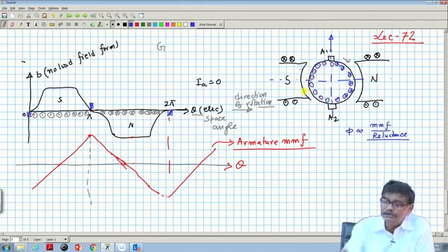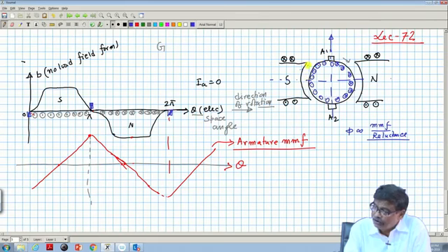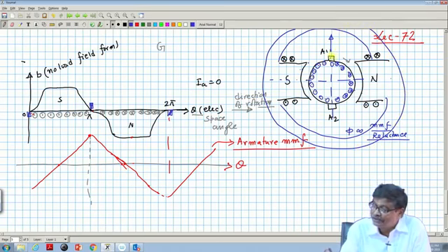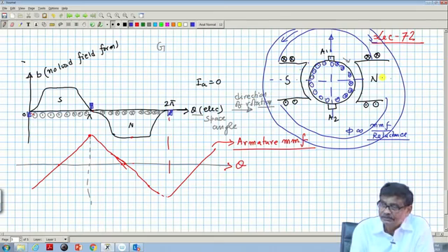But in case of a DC machine, one interesting thing happens. The air gap is more or less constant between this zone, but after that the air gap will be very large, because this is the yoke portion where the air gap is very large. Similarly, although armature MMF is acting, this is the yoke of the machine. Flux will continue its path like this and come back. This we discussed earlier. Therefore, the air gap is not constant.